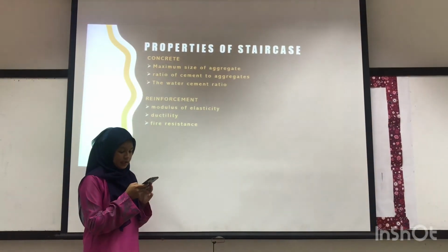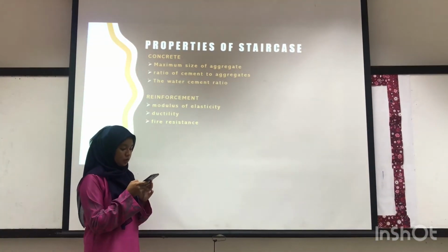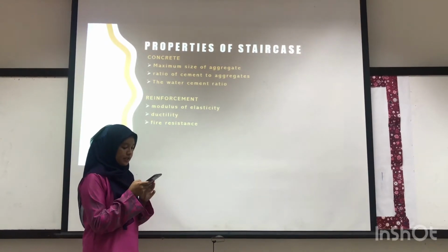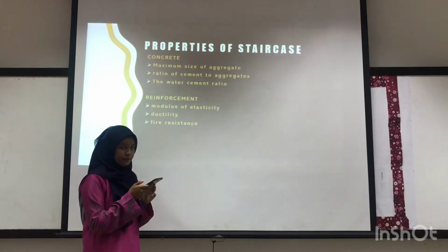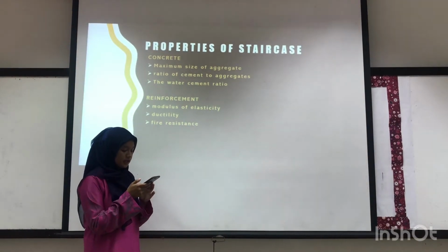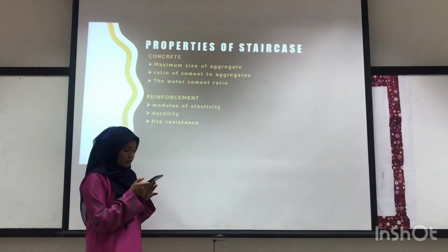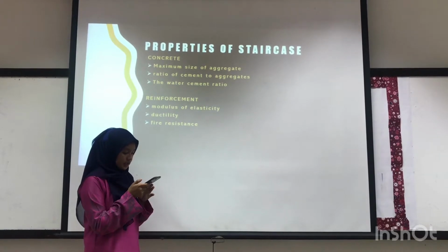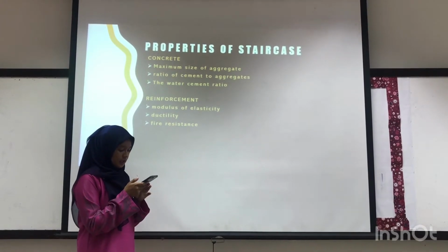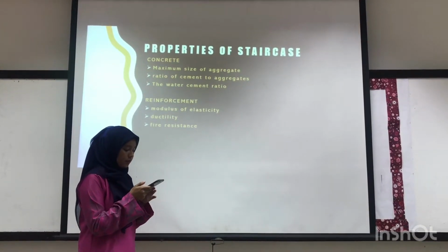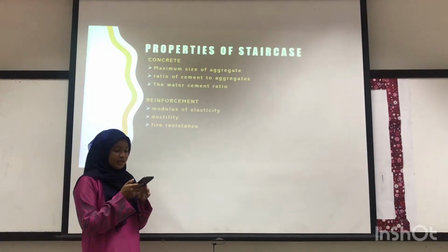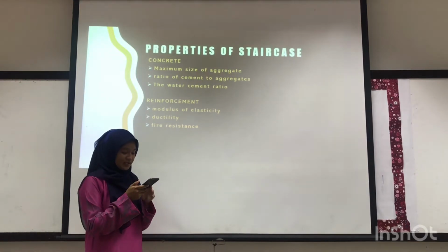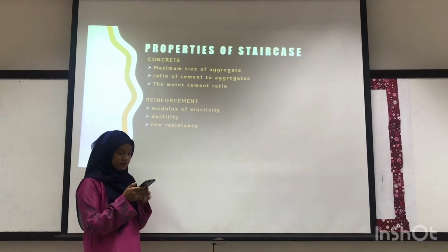Reinforcement structures that have been exposed to fire should be replaced because their working stress or permissible stress has decreased. Hence, in the construction of reinforced concrete structures, concrete covering is used to prevent heat from flowing to the reinforcement at a direct rate and to protect it from fire heat.